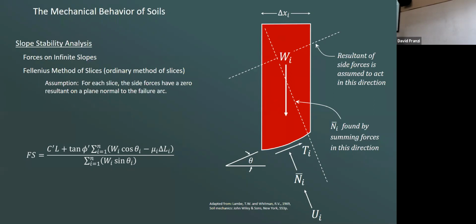We're going to take the normal stress, and by the way, that is the Mohr-Coulomb equation, is it not? C plus sigma n tan phi. We're going to use the Mohr-Coulomb equation to calculate the resisting stress, how much stress that particular slope can withstand before it fails. The cohesion part is C times the sum of all the little L sub i's. So the distance from, I should do this on the screen so you guys can see the cursor.